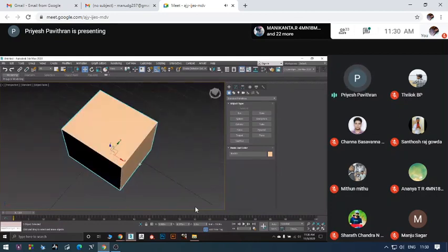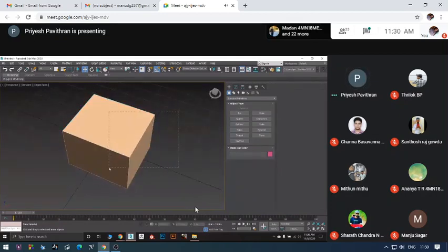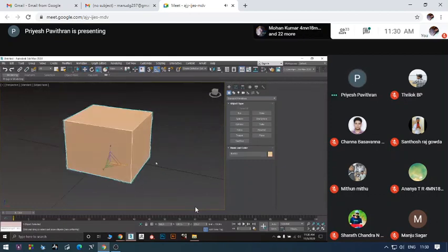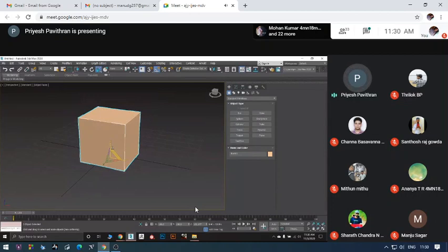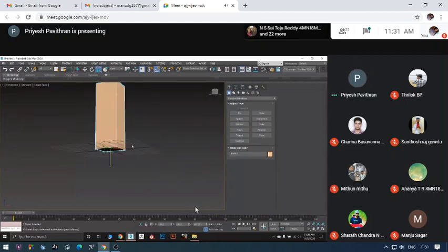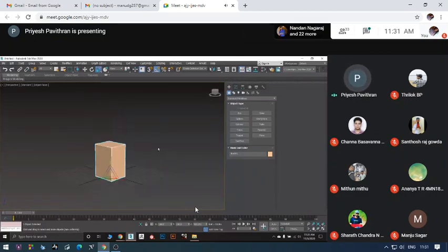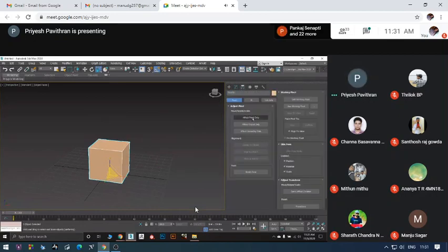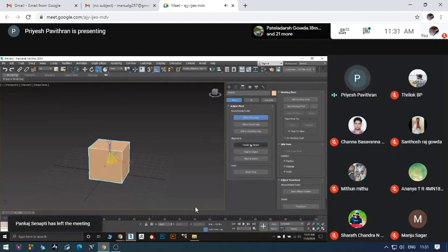Now in the perspective viewport, press R and move Z. It is only getting increased from the bottom. So to avoid that, if you want your model to be scaled properly, which means you need equal measurements on both sides, you have to fix your pivot. Just press affect pivot only, now center to object. Turn off affect pivot only.